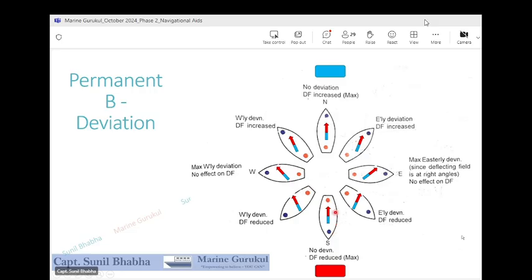So that is why they are not able to turn the compass needle by 180 degrees. If the ship's field was more powerful, it would turn the compass needle by 180 degrees and the needle would start pointing south. But since the magnetism of the ship is much weaker as compared to the magnetism of the Earth, they are not able to generate any deviation at all.